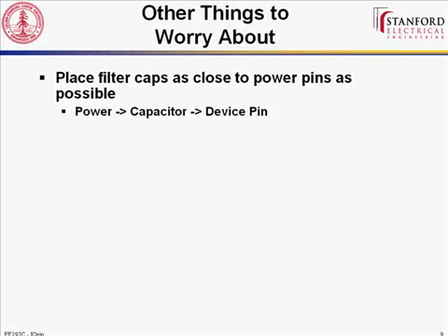So you want to place the polarized capacitor as close as possible to the power source, right? No. All three of those, the capacitors, go right next to each other by the device. Your power source will have capacitance as well before you enter your power plane or your traces. But the idea of having the tantalum capacitor, for example, the polarized capacitor, right next to the non-polarized, right next to the pin, is that the device will draw a current from the ceramic.